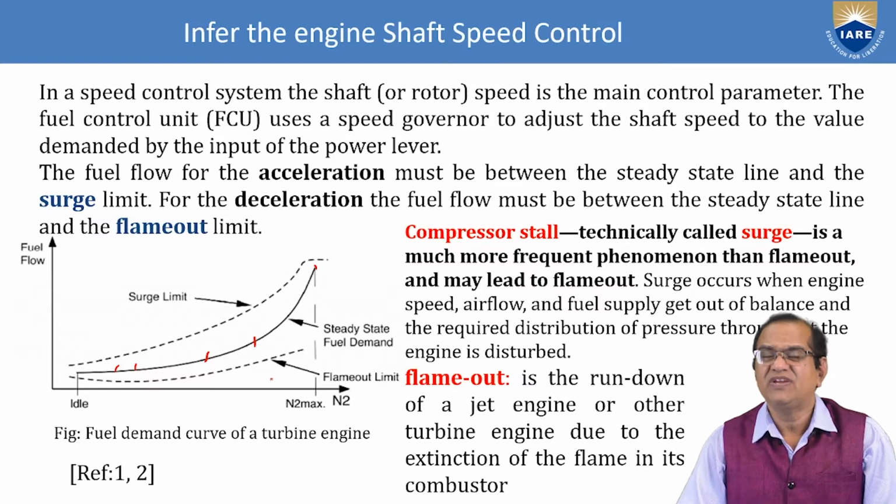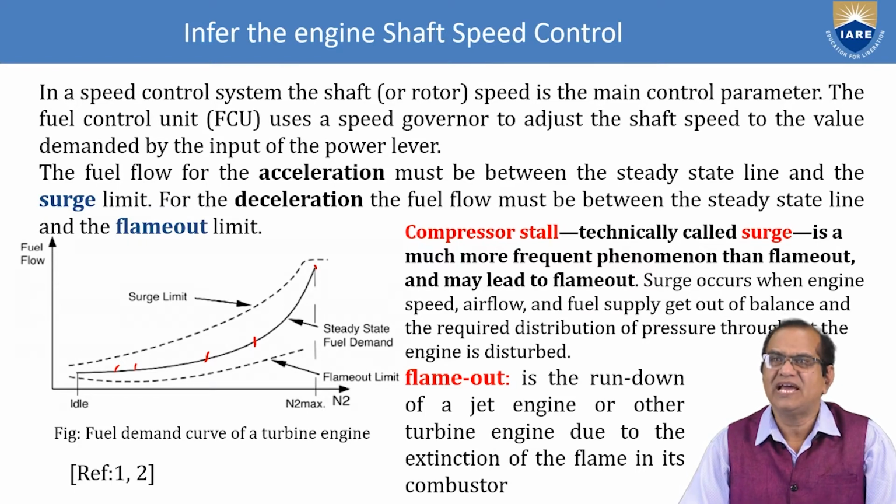Here we have one more term, called the compressor stall, which is also called the surge. It is a much more frequent phenomenon than the flame out and may lead to flame out. Surge occurs when engine speed, airflow and fuel supply get out of balance and the required distribution of pressure throughout the engine is disturbed.